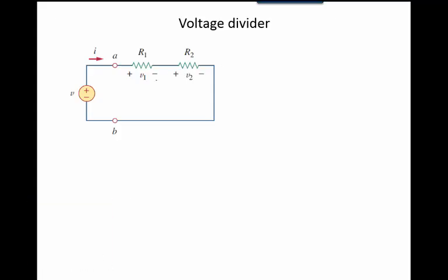Okay, so I'm just going to analyze this circuit. It is a loop circuit, so loops are Kirchhoff's voltage law, right? We like to use loops. Would you like me to analyze it with a clockwise loop or a counterclockwise loop? Do you care? You always do counterclockwise? I always do clockwise because that's the way I went to school. That's called the conventional current flow way, versus the other way, which is the actual electron flow way.